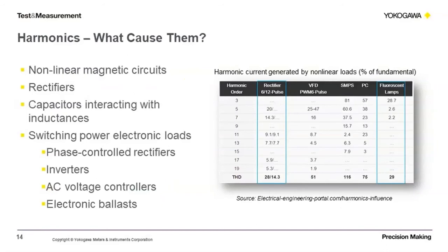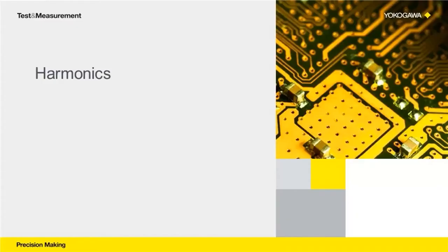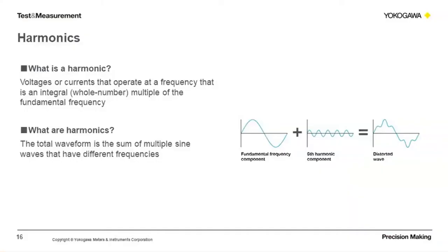Just how much distortion is caused by harmonics? Each nonlinear device has its unique contribution to harmonics with predictable behavior at specific harmonic orders. Next, we want to look at the harmonic waveforms and define sequences as it relates to the order or multiple of the fundamental. Harmonics refer to all sine waves whose frequency is an integer multiple of the fundamental wave, normally a 50 Hz or 60 Hz sinusoidal power line signal, or between 0 and 2 kHz for rotating machines.